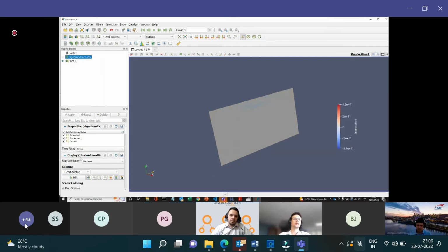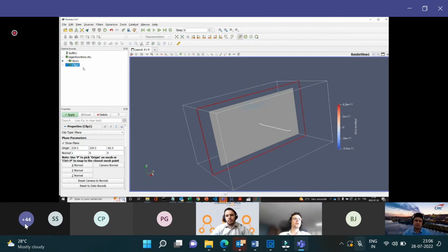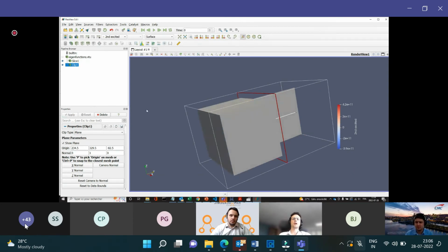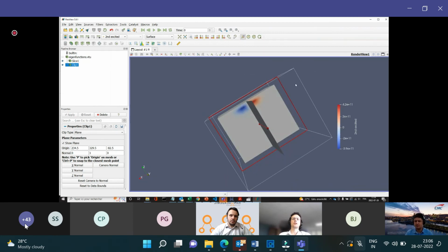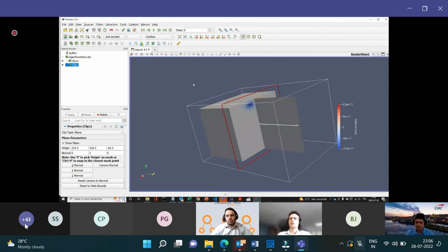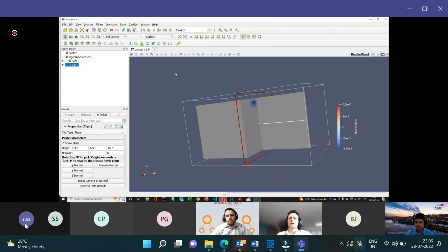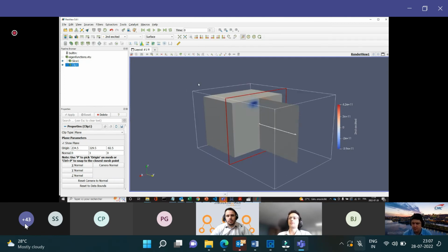So I actually need to do a slice which would be y normal. I click apply. I made a clipping instead. You can see the lobes are formed here. So I hope now to have convinced you that using Qtcad, simple Python scripts can be used to produce simulations of realistic structures, and then using ParaView, we can visualize the results in 3D and help understand if a structure is promising to host spin qubits.